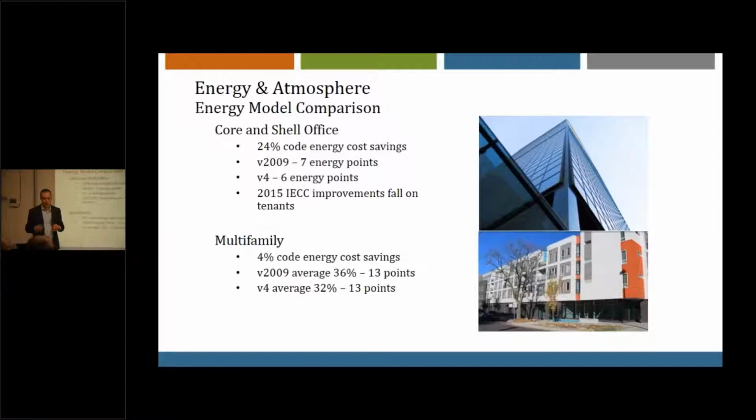The big reason for that, and I'll get into this more a little bit later, is as LEED shifted, at least in Denver, our baseline energy code shifted. So we went from 2009 IECC to 2015 IECC. Lucky for developers, a lot of these improvements for the office buildings fall on the tenant, not the developer, if they're doing a core shell type. If they're doing a full fit out, then it would fall on them, but the lighting controls and occupancy controls really fall on the tenant, not the developer.